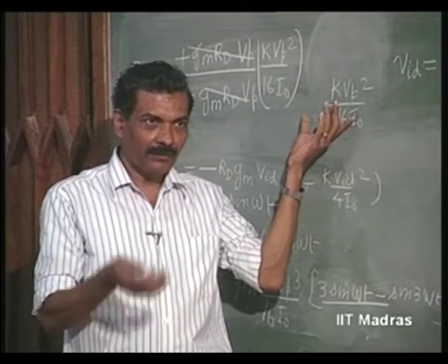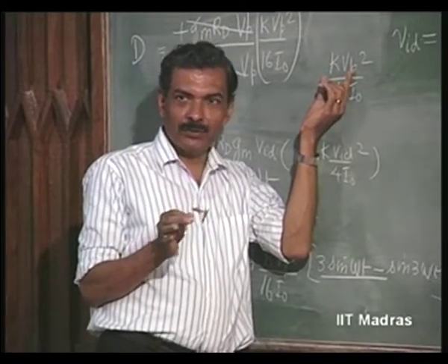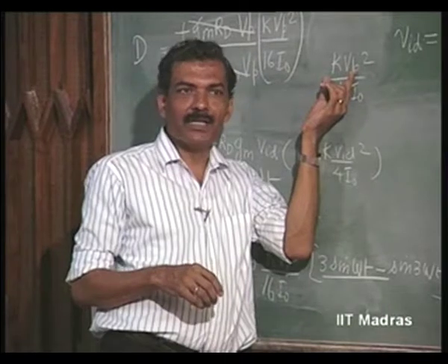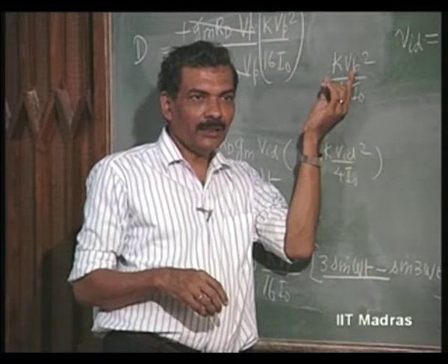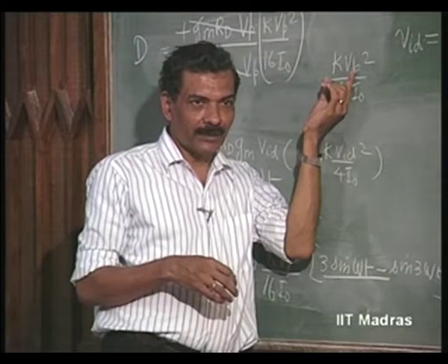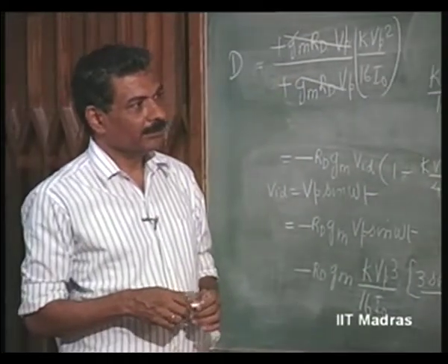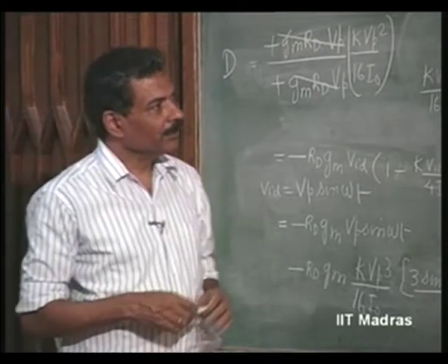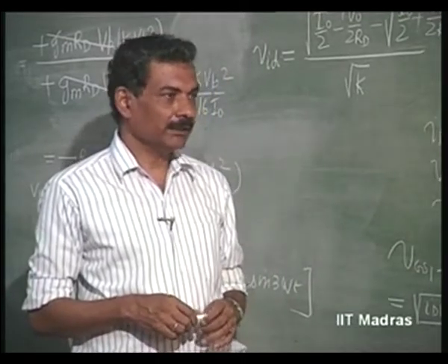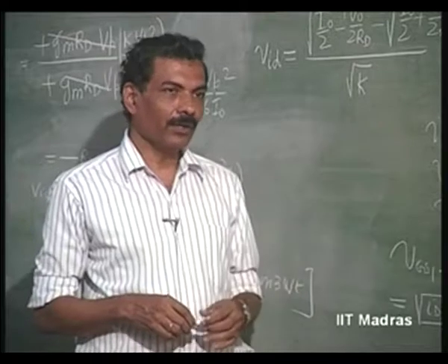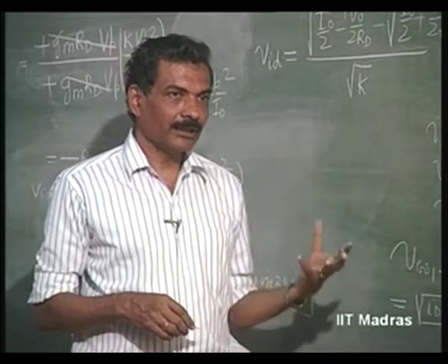Find out the V p required for 1% distortion at the output in both the cases and compare these, and you will definitely see that the differential amplifier is far superior to the common source amplifier. So, distortion wise this amplifier is definitely superior, and therefore, again we will never go for such common source amplifiers as discrete stages. We will go for the differential amplifier because it has superior large signal property.